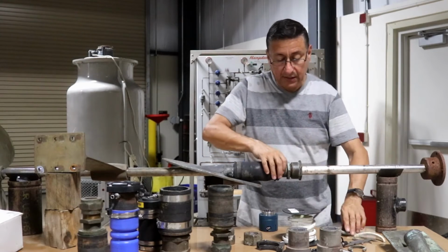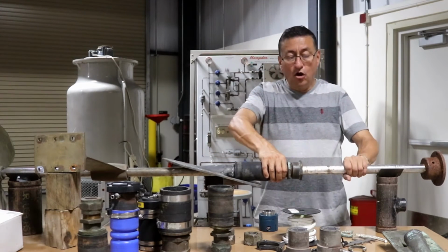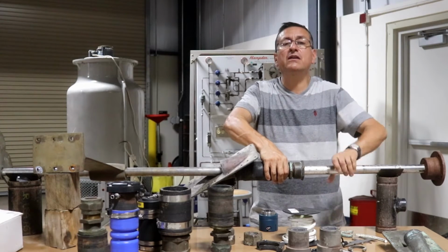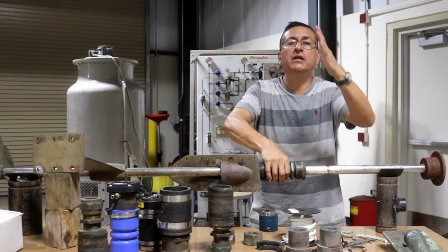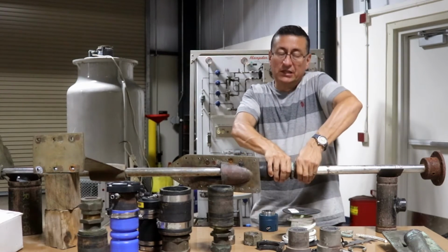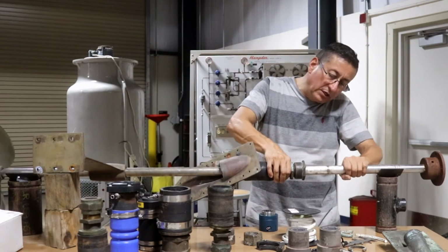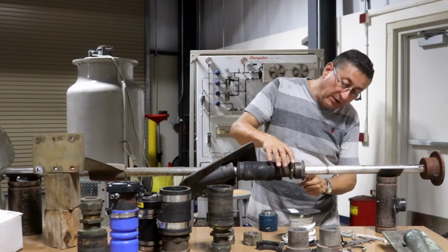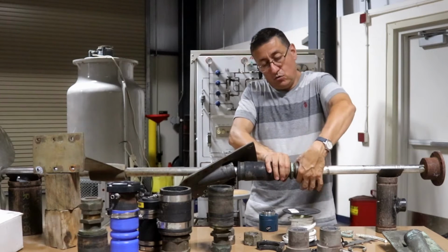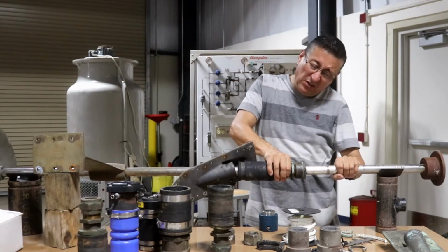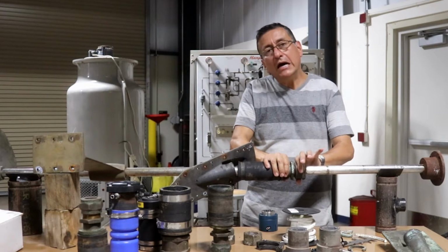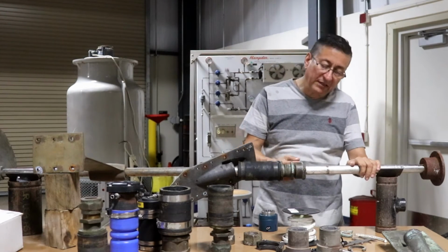Tighten, and always check that the system is rotating free, that the shaft is spinning with your hands. Once again, you tighten, and you tighten, and you spin with your hands, and you verify that you don't have leaks. If suddenly, when you tighten this one, it's impossible to turn the shaft with your hands, you need to loosen a little and verify that you don't have leaks.